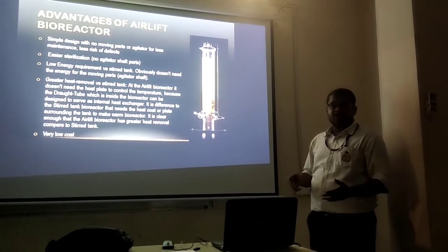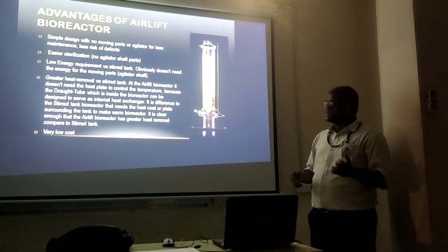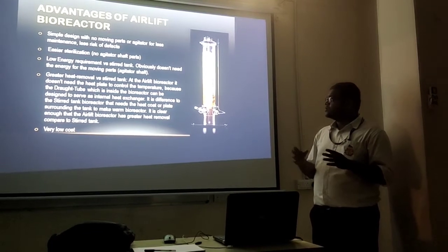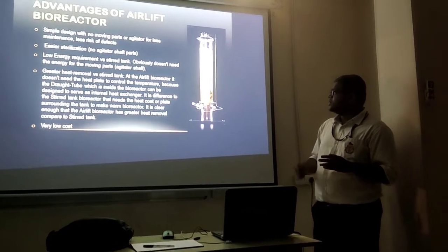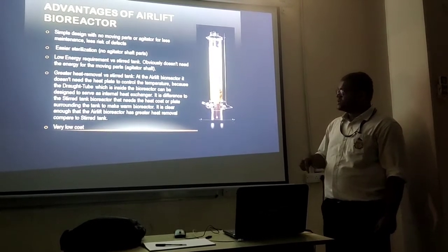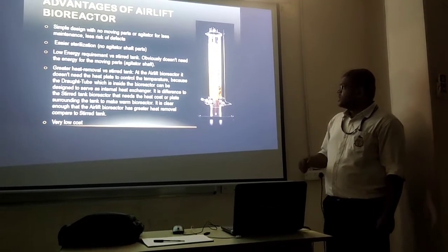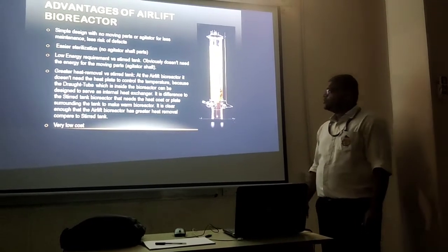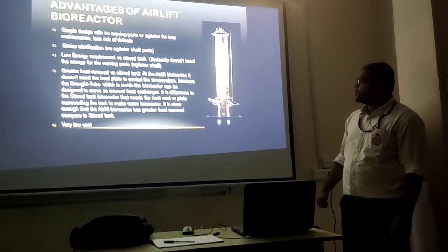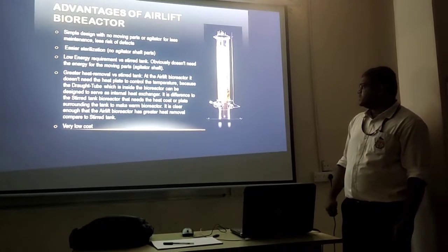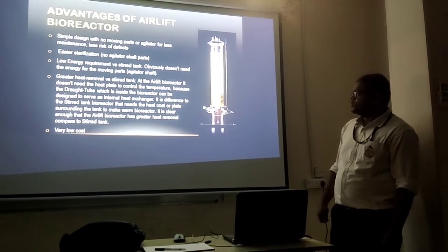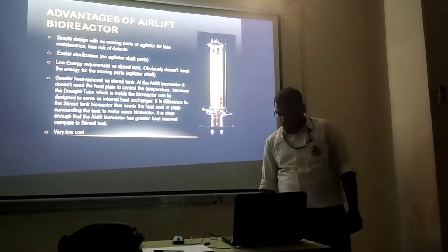The draft tube inside the bioreactor can be designed to serve as an internal heat exchanger. This is different from the stirred tank bioreactor, which needs a jacket or plate surrounding the tank to warm the bioreactor. It is clear that the airlift bioreactor has greater heat removal compared to the stirred tank, and it is also a low cost